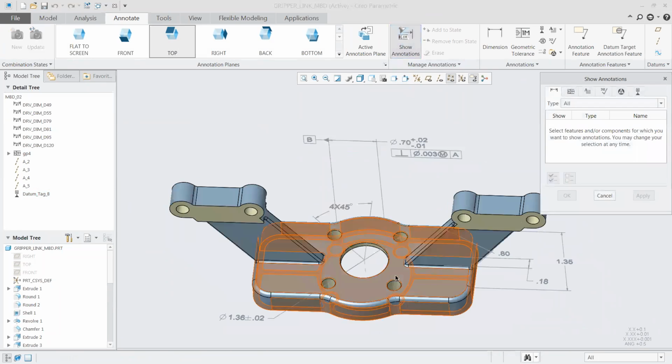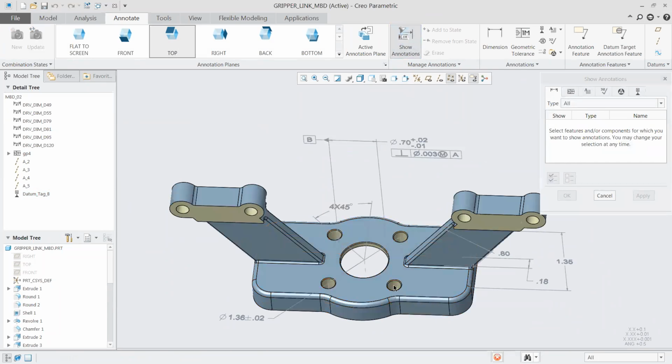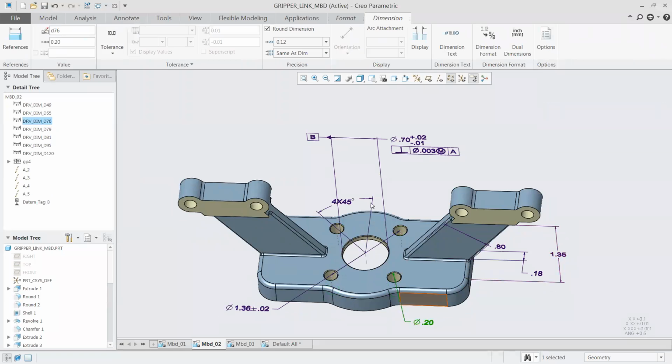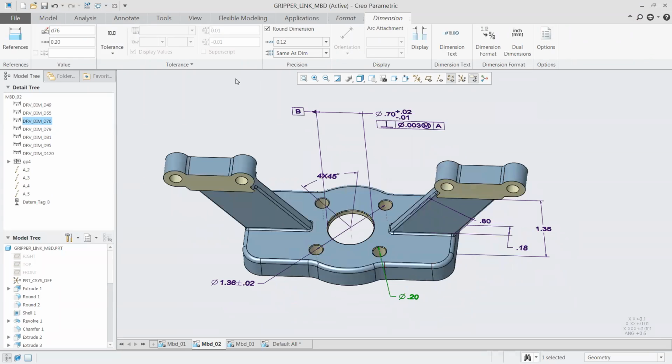So from there, we can go ahead and work with some of the definitions around our mounted holes on the outside. So we'll start first and foremost by getting our diameter dimension here, dragging that away from the model. And just like we did with the other hole, we can lay out a range for that value. We can even define exactly how many decimal places should be displayed on that as well. And we can go through and make whatever additions that we might need to for those tolerances.